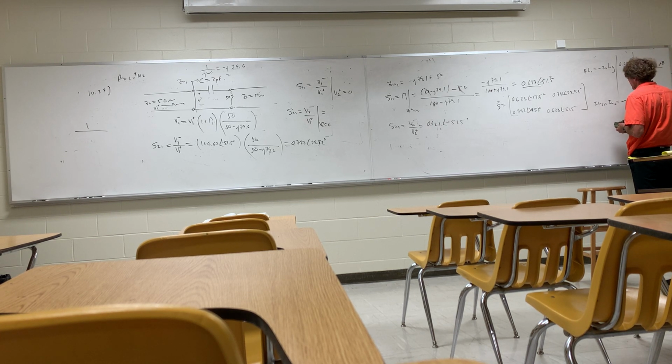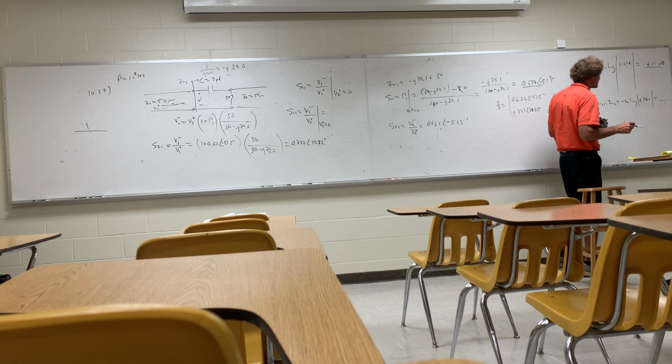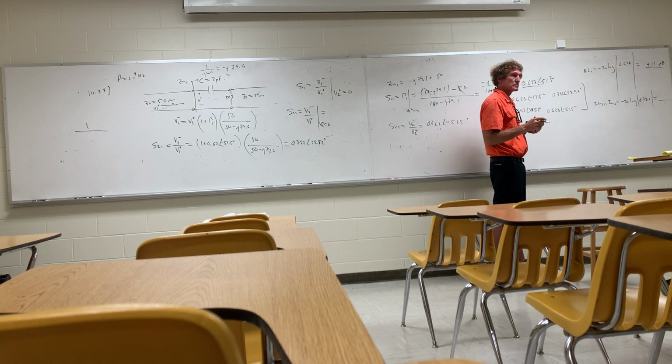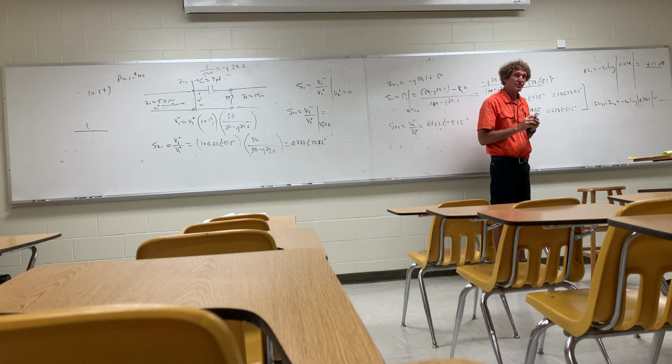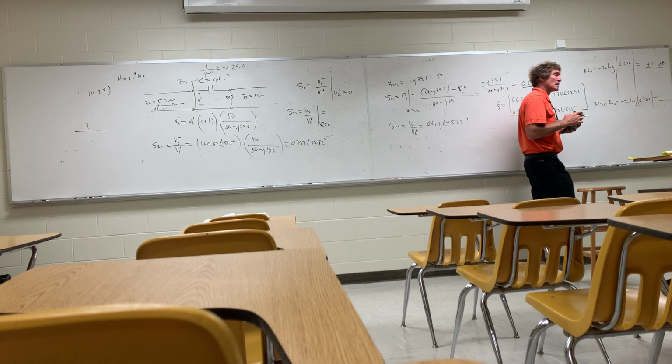And this is for the insertion loss: it's minus 20 times the log of the magnitude of S21 or S12, which is 0.782. And give me that. That's log base 10, remember that, not natural log. If you use MATLAB, LOG in MATLAB is log base e. You have to put LOG10 if you want log base 10 in MATLAB. Remember that when you're doing your projects. 2.76.